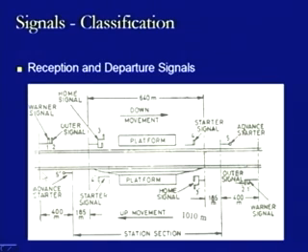If we assume that this line is also being used for the down movement, then there is a possibility of stopping the signal at this section or at this section. So, we have two lines, and in that sense we can have two arms like this, segregated by two bases. So, we have two base systems like this, and on each base system one signal is provided. If this goes down, it defines that the train is supposed to take this loop line section, whereas if this goes down, it defines that it is to take the main line section, or similarly on this side.